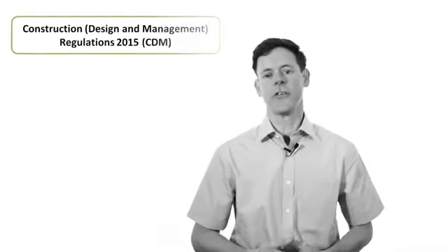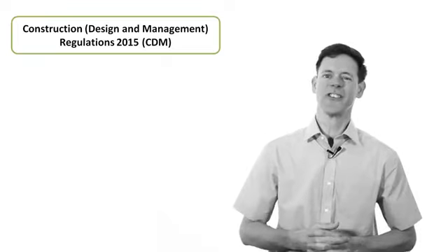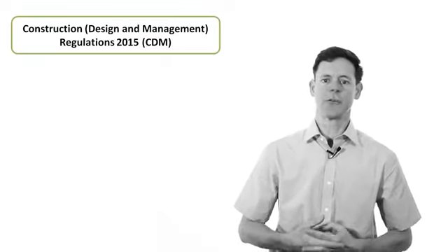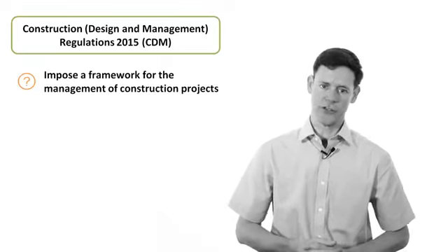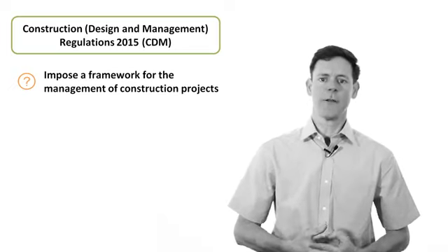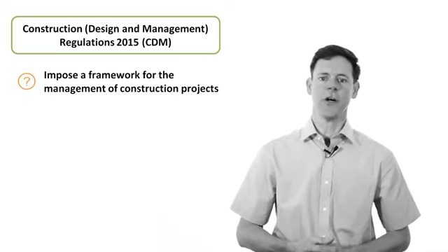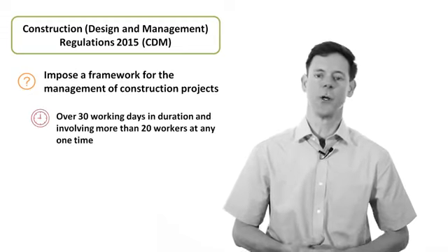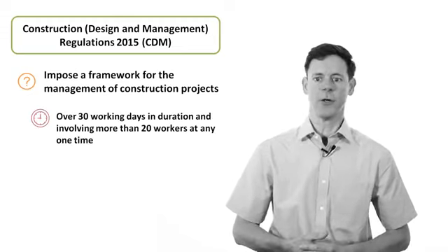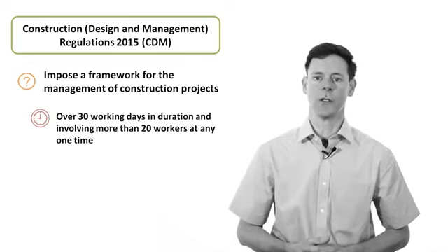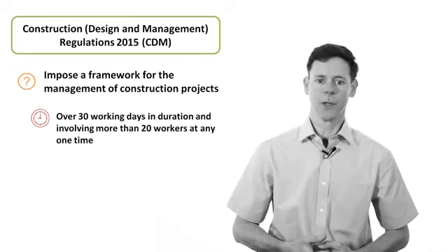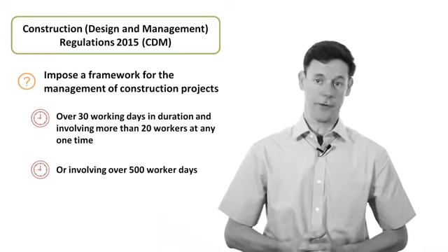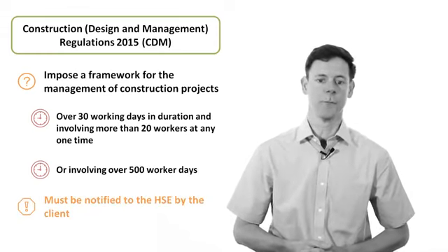The Construction, Design and Management Regulations, or CDM regulations, establish a framework for the management of construction projects. The regulations require that certain construction projects are notified to the Health and Safety Executive. Specifically, projects which are over 30 working days in duration and involve more than 20 workers at any one time are notifiable. Also, projects involving over 500 worker days are notifiable.